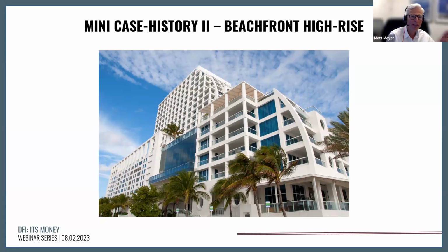What we're going to be talking about today is how to properly delineate a deep subsurface condition, and how, through a phased extensive subsurface investigation, to properly delineate that zone of poor subsurface conditions relative to the tower structure, and how to vary the lengths of the piles within the tower proper itself and achieve capacity and settlement compatibility. And I think you're going to see that as I walk you through the next several slides.